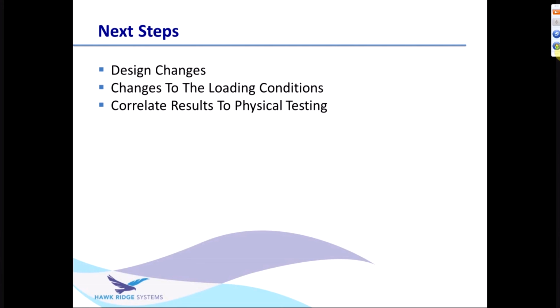In the case of Ingersoll, one thing we could have done is correlate the stiffness we used in the spring connectors to a physical test of the actual linear rail or ball screw assemblies, so that we can adjust those stiffnesses, essentially providing more realistic results where we're not, in a way, doubling up on the stiffness by including the components that made up those linear rails and ball screws.